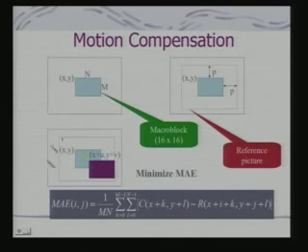So, we have to search around this, and at each position of this anchoring point, I need to compute this function. Fine. This is actually an absolute error, okay, summation of absolute error over each pixel in the macro block. Is this clear? And I would like to find out u and v, which would minimize this.